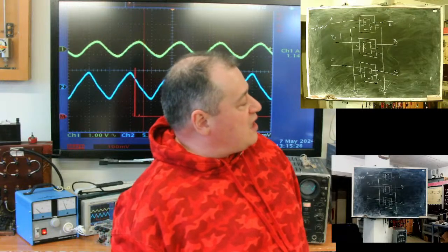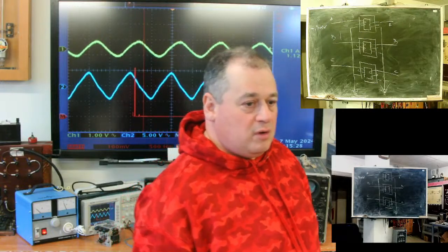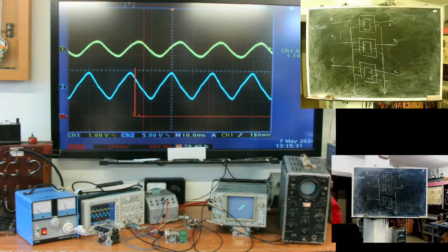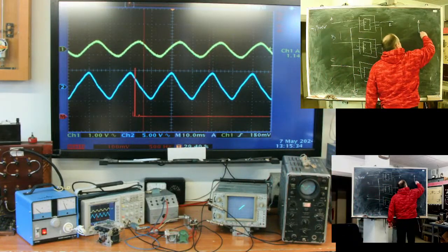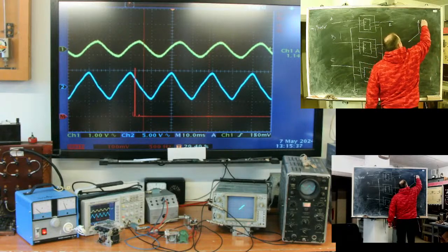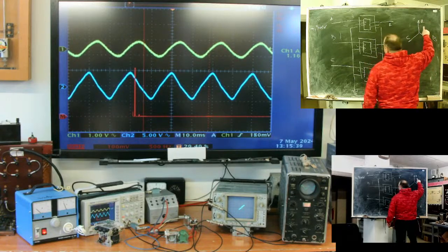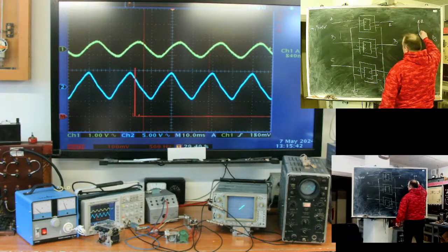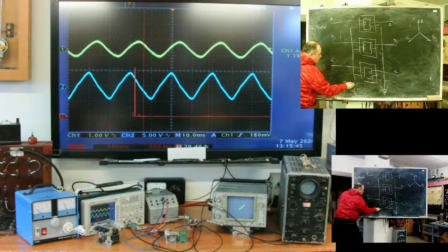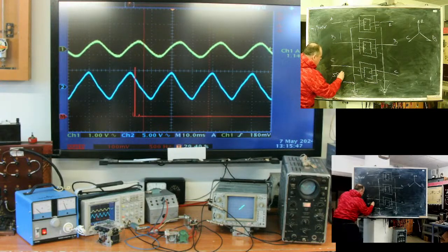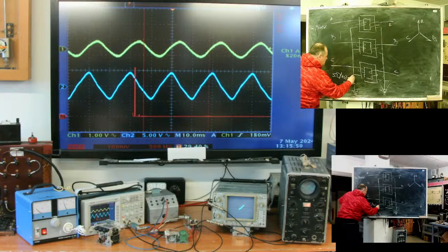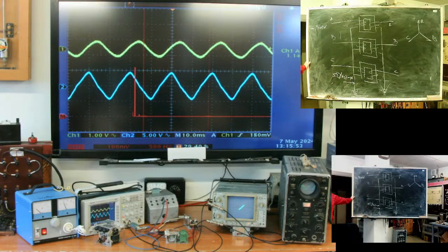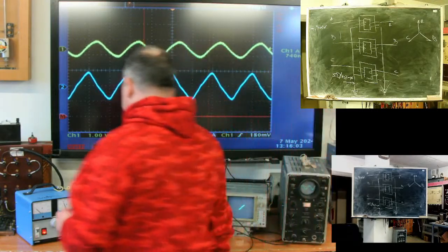How will the 150 hertz component flow? Here, at 50 hertz, we will have a nice A, B, C star, and if we sum these vector currents, the current here at 50 hertz should be 0, if we have equal transformers. Each pole has its own transformer, but let's assume they are equal.